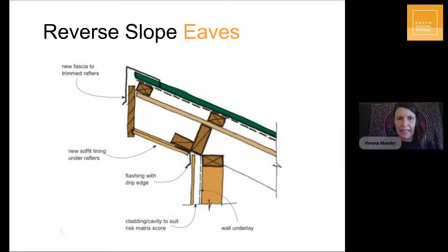So that is called a flashing. It has a little drip edge, and it protects material junctions from water ingression, because especially if you have wind with your rain, water just has a way of finding its way into the structure. So these flashings are very important. They are an added cost, but they really are recommended.